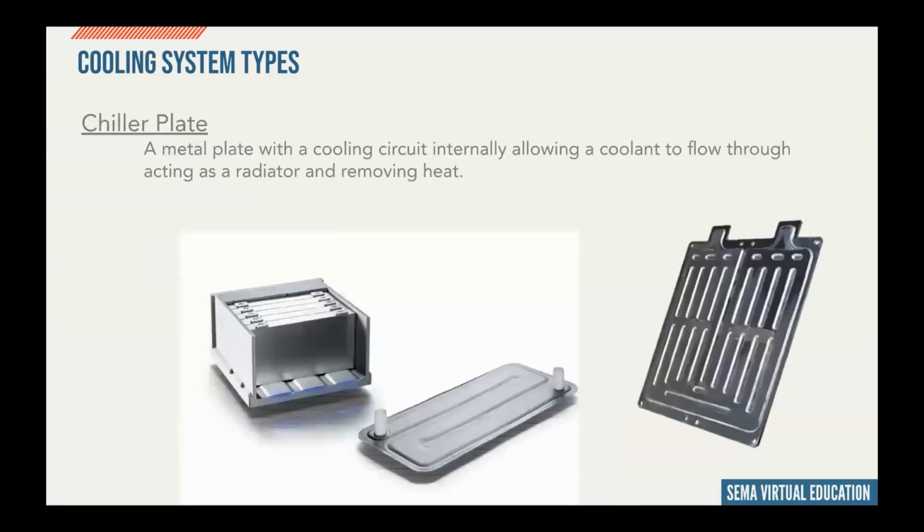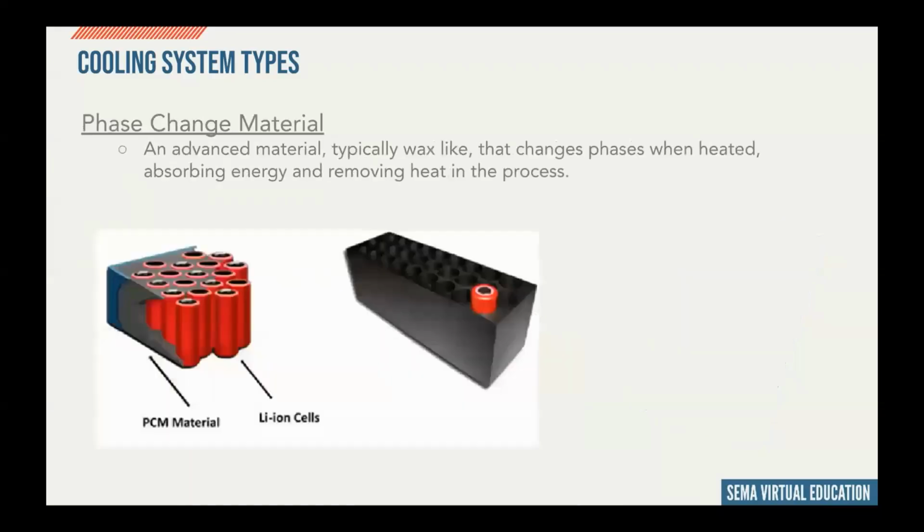Chiller plates are one of the more user-friendly and easier things to design or fabricate. They do not have a very significant way of pulling heat out of cells, because they are touching one surface or one face of cells. But chiller plates can be a very good way to do a battery pack design at lower cost.